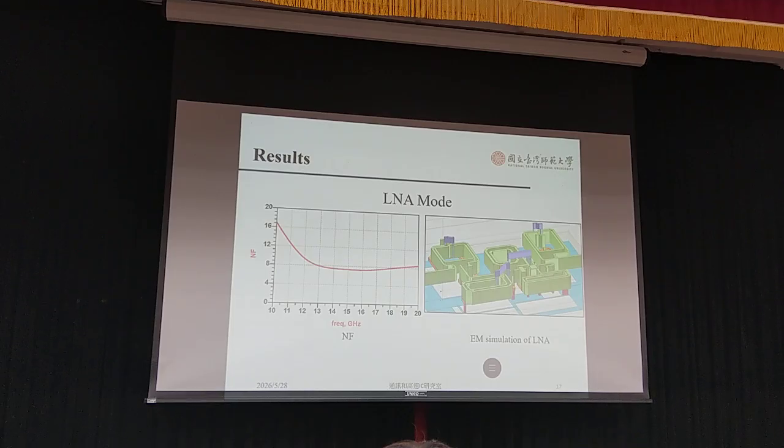The minimum noise figure is about 7 dB. Although this is not an ultra low noise design, we should remember that this is an integrated bidirectional front-end architecture. The DC power consumption is only 12 milliwatts, which is one strong point of this design. Overall, this LNA provides a good balance between gain, power, and integration.